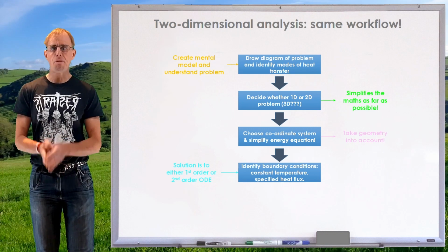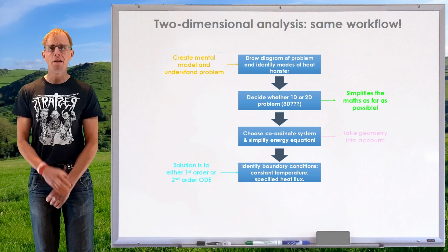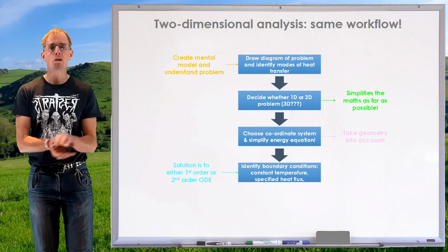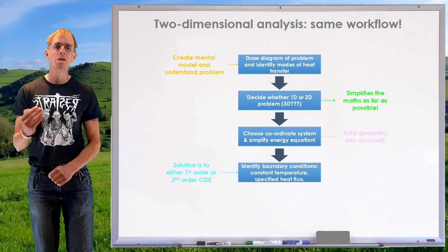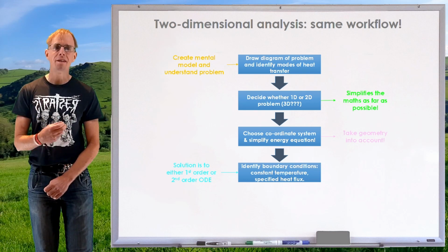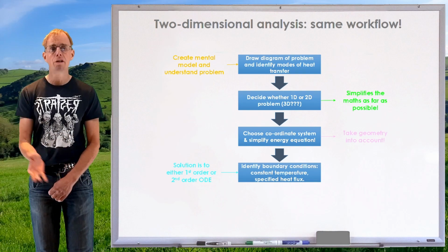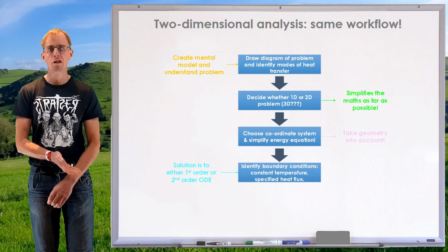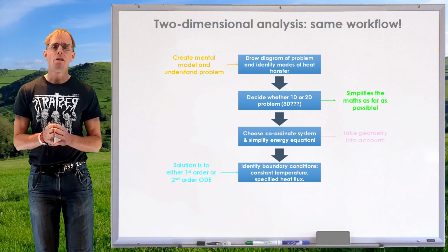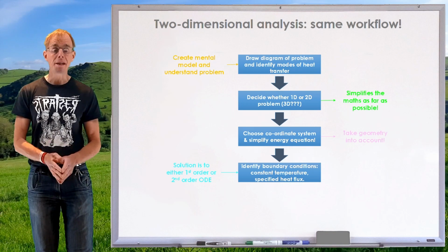And if we're losing heat in direct proportion to that, then the object's going to cool, but that driving temperature difference is going to be reducing. And so as we move along the extrudate, proportionately, we expect there to be less and less heat transfer. Therefore, we expect a nice curve of a temperature gradient, a reducing curve. So create that mental model. Try and foresee what the answer you're going to calculate or compute is actually going to be.